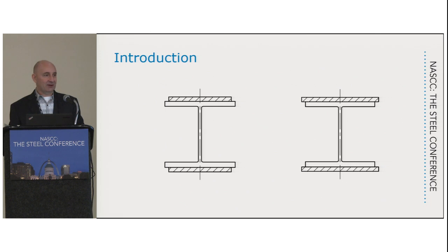The one on the right-hand side, if I need a little more strength or buckling stiffness for buckling about the y-axis especially, without increasing the plate thickness, I might go to the one on the right. But that one's a tiny bit harder to install sometimes, because a lot of times you're going to have members framing into the web of that member. You'll have beams and struts framing in, and potentially vertical bracing gusset plates. In the first case, the welder is just out here and has a lot of room to weld, and in this one, he might be slowed down a little by the obstructions in the web. So that's why that's kind of my second choice.